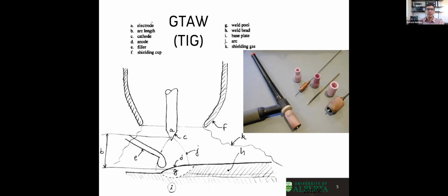So here's a little bit of a summary of what I was talking about. The way we protect the molten metal is with an inert gas in this case. Typically it is argon. If instead of argon, we would have something that is reactive, like a little bit of oxygen, this would react with the tungsten and ruin the tungsten, because tungsten is also very reactive.